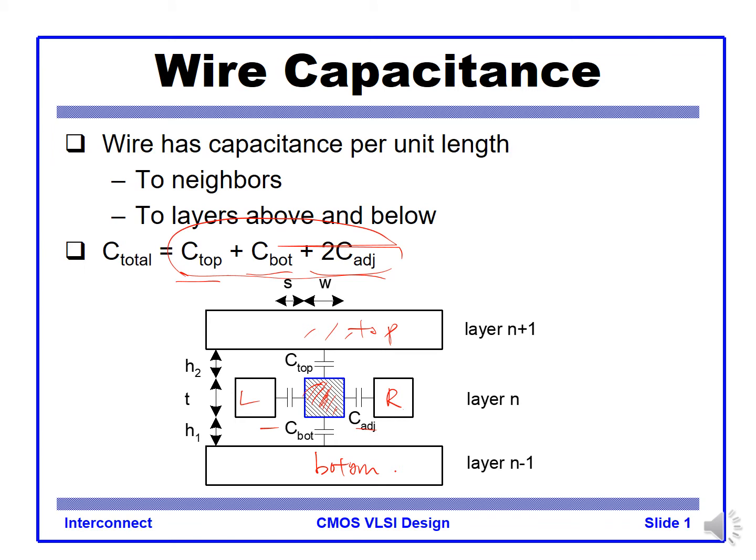capacitance. So when you draw the signal line, try to minimize the coupling capacitance. We want to minimize it there. The worst case happens when you run the signals in parallel, because then you see a lot more facing area, which gives a larger capacitance.